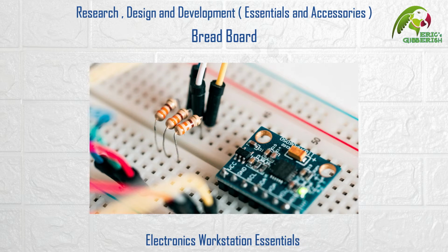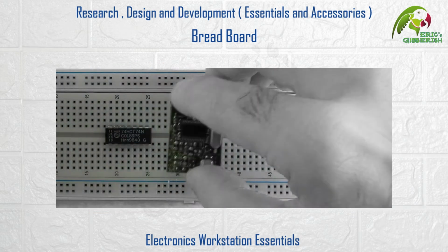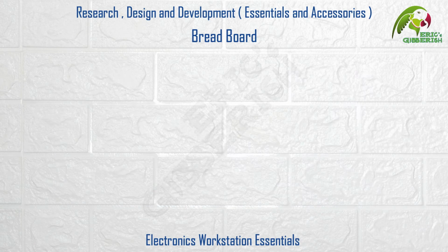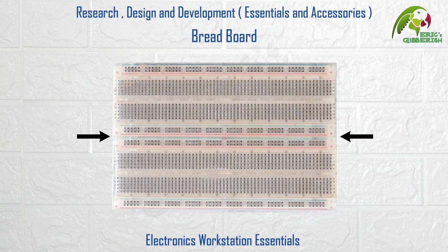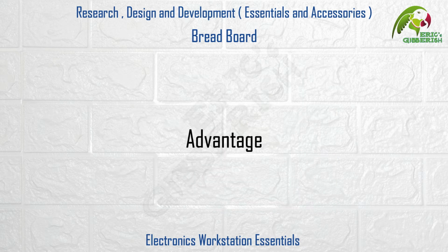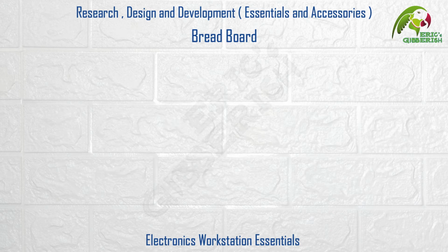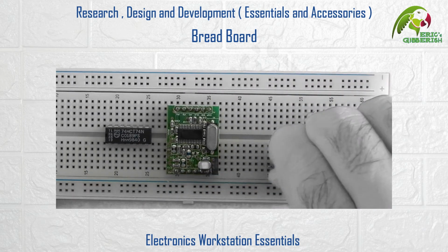Breadboard. The breadboard is a solderless device used to build prototypes and lesser complicated electronic circuits. It has a number of holes or sockets into which you can insert most components, devices and modules. Breadboards are available in various sizes, and they have these tabs and notches on the sides using which you can snap or join multiple boards together. The advantage of using a breadboard is that the connections between the various components of the circuit built on the breadboard are not permanent, and hence the breadboard can be reused many a times to construct various circuits and prototypes.